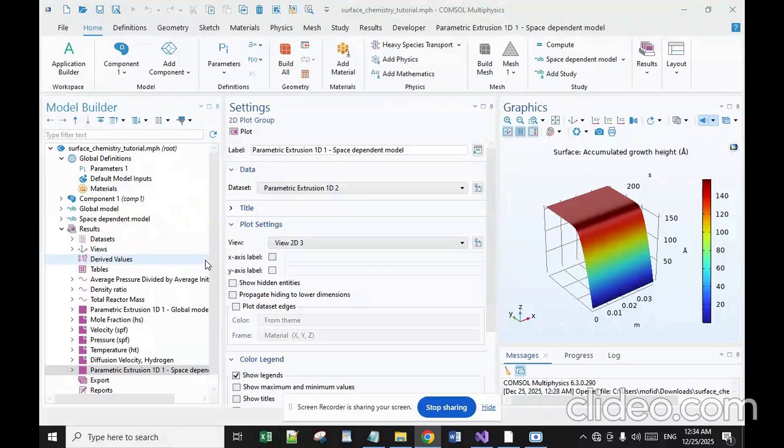Chemical vapor deposition, or CVD, is a vacuum deposition method used to produce high quality and high performance solid materials, and the process is often used in the semiconductor industry to produce thin films. In typical CVD, the wafer substrate is exposed to one or more volatile precursors which react and/or decompose on the substrate surface to produce the desired deposit. Frequently, volatile byproducts are also produced, which are removed by gas flow through the reaction chamber.